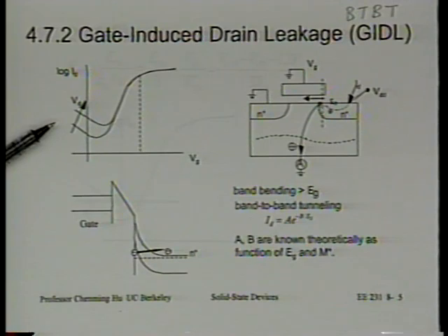So subthreshold current refers to the mechanism we just finished discussing. This one, although it happens at VG below VT, it's best not to call what we're going to speak about now subthreshold current. You know what I'm trying to say? It is subthreshold, but the term has a pretty specific tie to that particular mechanism we just finished talking about.